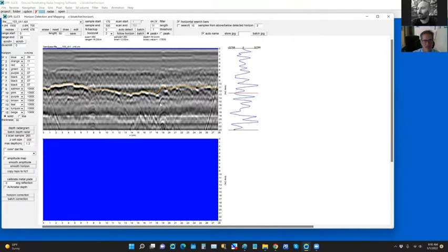Right now, it's set to 50 scans, so it's doing a kind of large swath of data. Let's say you want to have more detail when you're editing it. If I put it down to 5, and then I come here, you have a lot more detail that you can put into the profile. So it's your trade-off of what kind of resolution you want to put into your profile. Okay, I'm going to put it at like 15, and then just edit this right here.